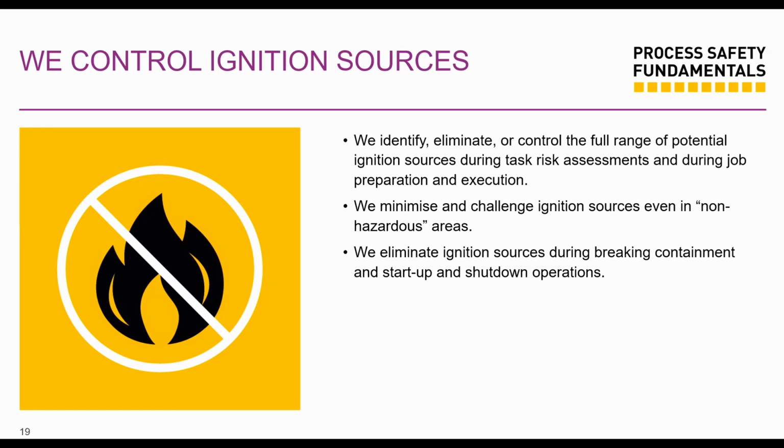That work should be immediately postponed, because we've had lots of incidents happen that way. Guess what? The area has not been purged and isolated. Go back, do a purge, and make sure you're properly isolating it to ensure that we don't have flammable gas or toxic gas in that area.